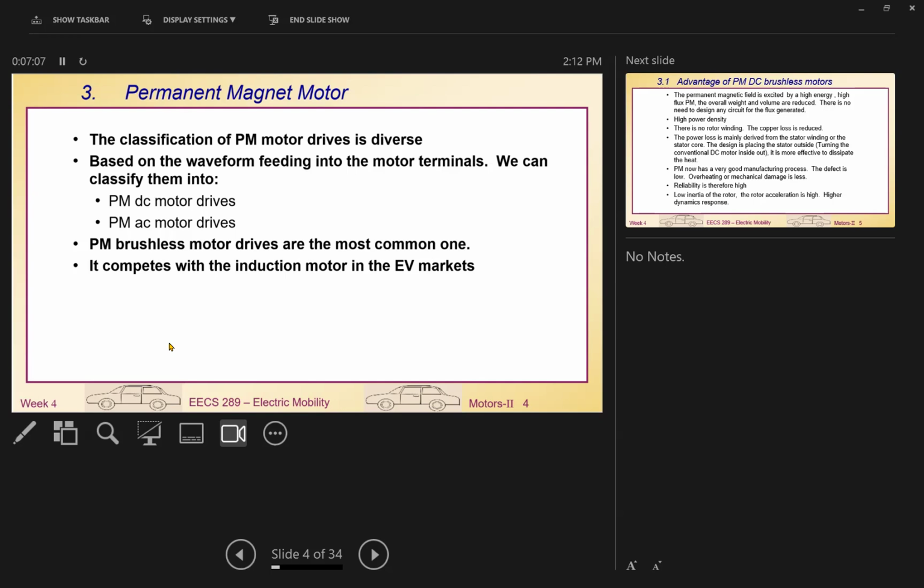It's not really a torque issue, it's another issue. More in the industrial side, something with the power rating. You see, an SUV usually has about 100 kilowatt power. And if you go to a truck, they usually need 300 kilowatt, 500 kilowatt, high power. Then the permanent magnet will also be quite large and quite big. PMs use rare earth material. They're very expensive. That's one thing.